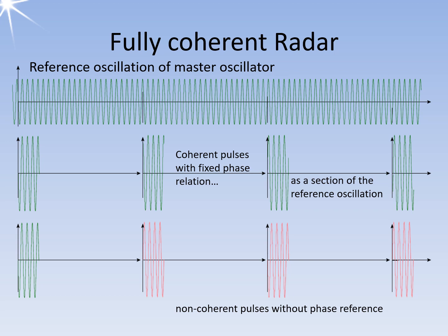Non-coherent radars use a high-power oscillator. In the very high frequency range, this can still be a triode or tetrode. At higher frequencies, it is usually a magnetron. The phase position at the start of the oscillation in a high-power oscillator is undetermined and chaotic. This means that no Doppler frequency can be measured, and thus, moving targets cannot be distinguished from fixed targets.